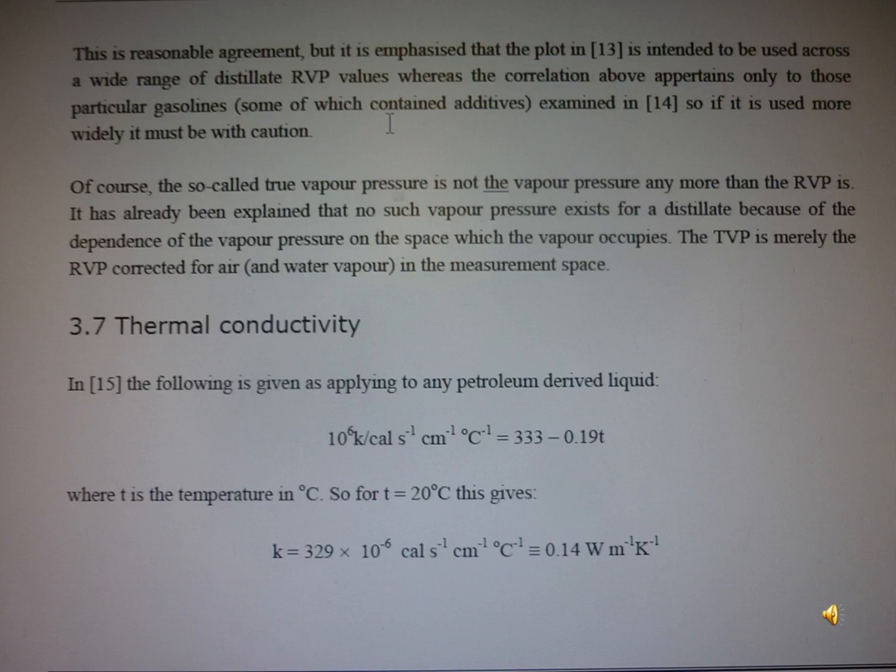The typical density for kerosene jet aircraft fuel would be 780 kilograms per cubic meter, or 50 degrees API. Of course, there is a large difference between the temperature at which the aircraft on the ground receives fuel and that at which the aircraft cruises. At a cruising height of 10,000 meters, the temperature is way below minus 50 degrees centigrade. The calculation performed in section 2.1.3 for crude is repeated below for the kerosene.